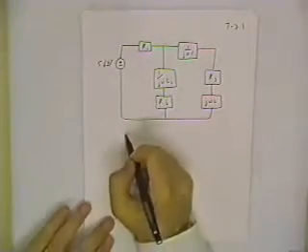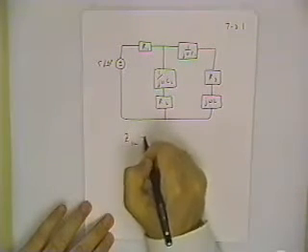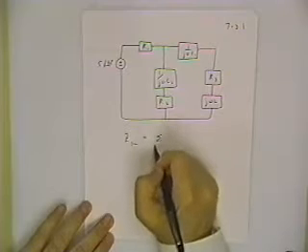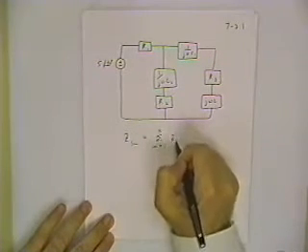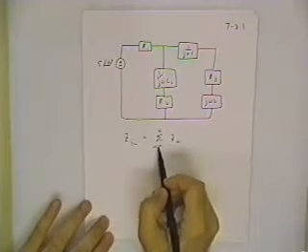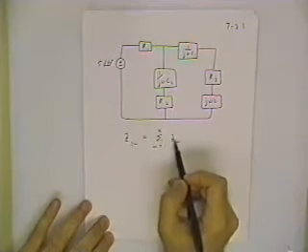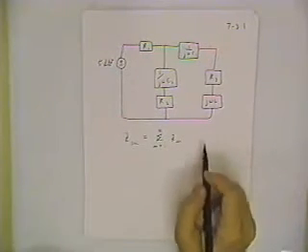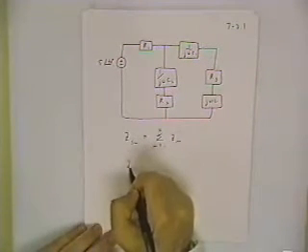And that's a key concept: in series connected impedances you have the same sum rule we had for series connected resistors. If you have capital N impedances all in series, you just add them up algebraically, remembering to group the real and imaginary parts. You come up with a complex number equivalent here.